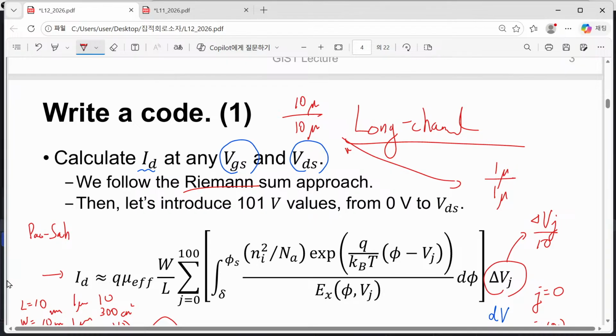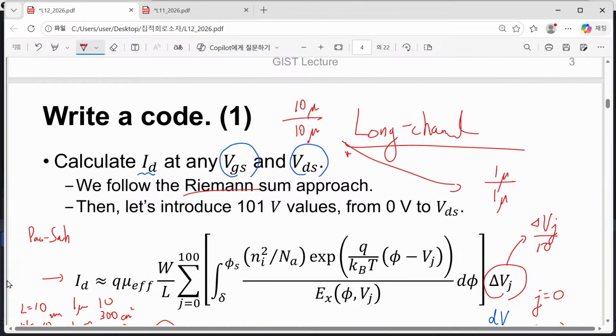So there is a scalability. This is huge. If you reduce it by a factor of 100, reducing the length 10 times and the width 10 times, then your transistor will conduct exactly the same amount of current at a given bias condition. That is the assumption, or the theory, for the long channel MOSFET. This is really difficult to believe, but it's true in the long channel limit.